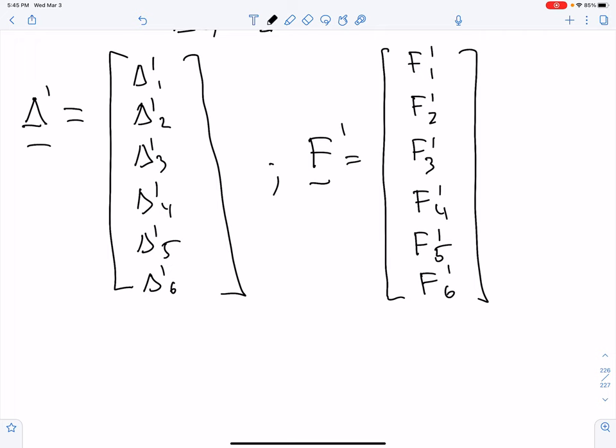Now, just like in the case of trusses, we want to relate the two. So we're working with a basic system, a local system, and a global system. The way we're going to build up our analysis framework is we'll start in the basic system, convert to local, then convert to global. This will give us a stiffness matrix for the situation, and then that stiffness matrix gets shipped to its global counterpart.